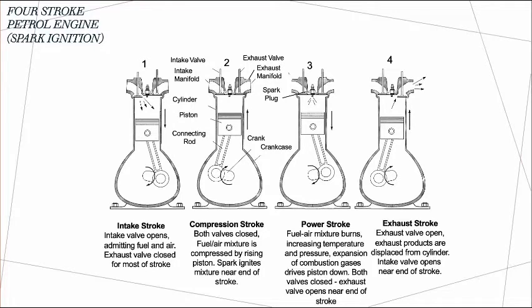degrees. And the second is the compression stroke. Here, the piston moves from the BDC to the TDC, compressing the air-fuel mixture, and the momentum of the flywheel helps the piston to move upwards. During this stroke, the intake valve is closed, the exhaust valve is also closed,